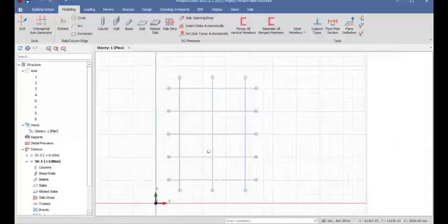That is one of the disadvantages of importing. For a complex structure, it's ideal that we use the DXF format, but it will take you time to edit the whole grid lines of the complex structure to put them in order. That is what I'm trying to explain here.